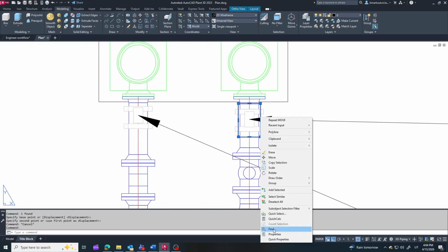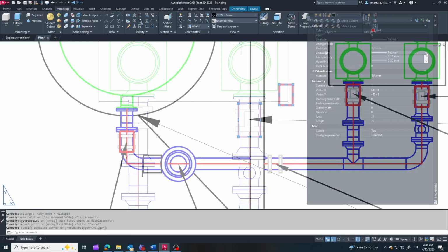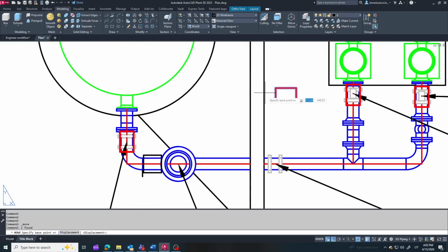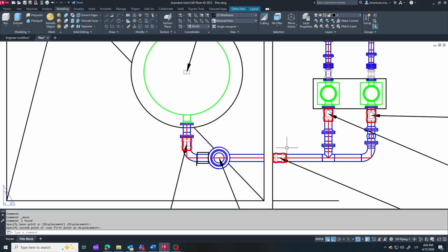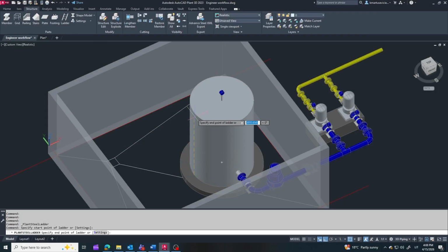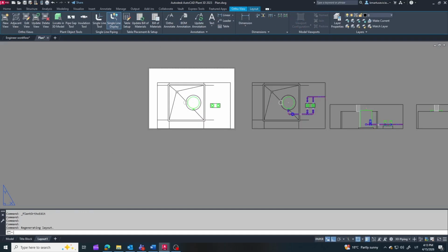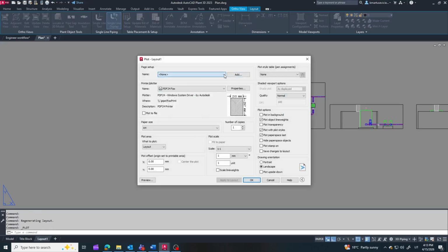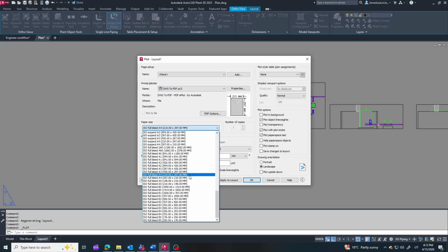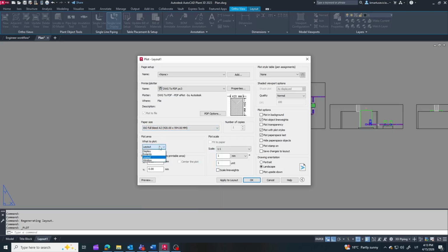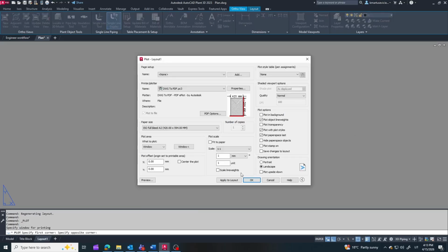So, the tasks for this small unit are complete. Now we add a ladder to the top of the tank to provide access to the level sensor. And finally, we prepare one layout drawing that combines all plans and section views, just like in a real project. I create an A2 size sheet to see how all the views are arranged on it for better visualization. When preparing project drawings, frames are also required. This time, I'll just use a simple black frame.